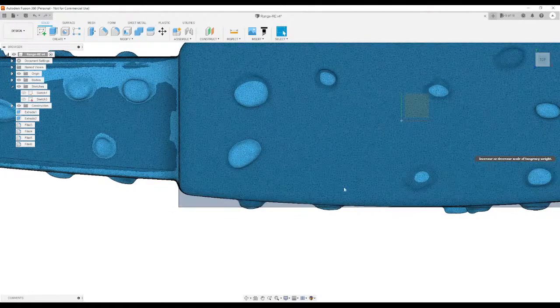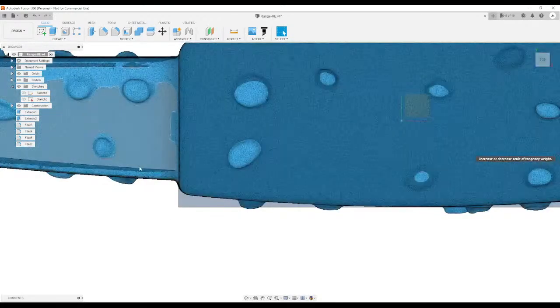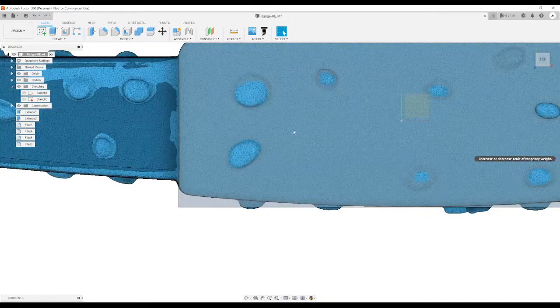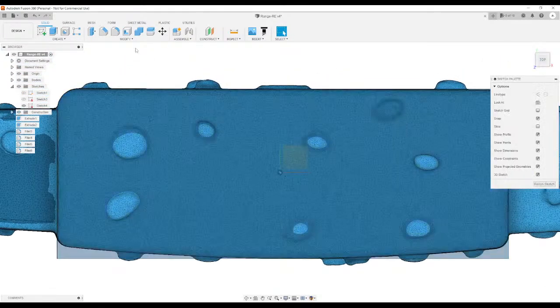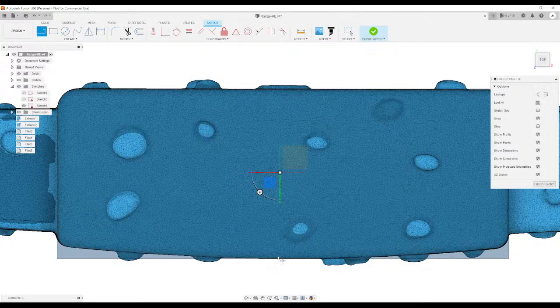This is basically the same thing that we did on the initial model, but since we already have this mesh cube here, now we will do a new sketch. Select line, use the center point as a reference, the middle point, that triangle there is the middle point, and click and drag. Okay, it's not working. When it doesn't work like this, we just do a line backwards.